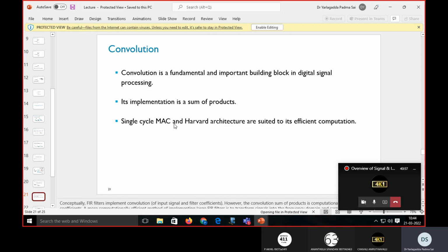Like that, different address buses are available. In the fixed point 54x, 4 buses are available, so you can execute 4 instructions at a time. Whereas in the 6x, which you already studied, you have 4 dot units and 16 registers available, an A side register file and a B side register file. You can execute in parallel, so all those advantages are there.